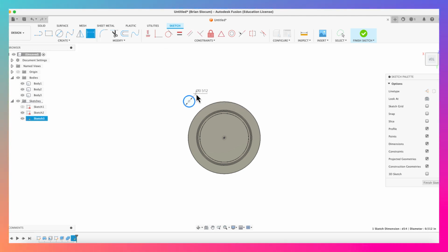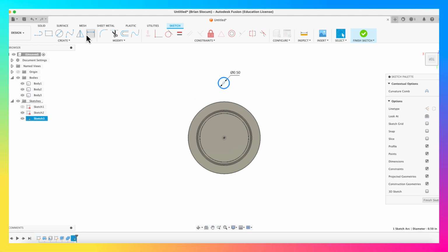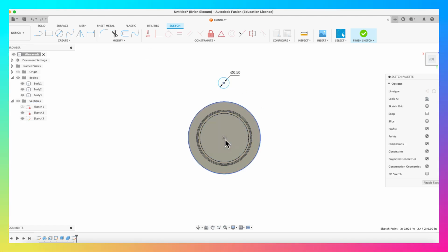And we'll make this, we'll say 0.5 inch seems good, 0.5 inches. And let's position this in space somewhere, so I can move this all around. I'm going to position this so that it aligns with my origin point, just because I need to constrain it somehow. So I'm going to click on that. I'm going to hold down Shift, click my origin point, and click horizontal and vertical, and that locks that. So I can't move it left to right, but I can move it up and down.